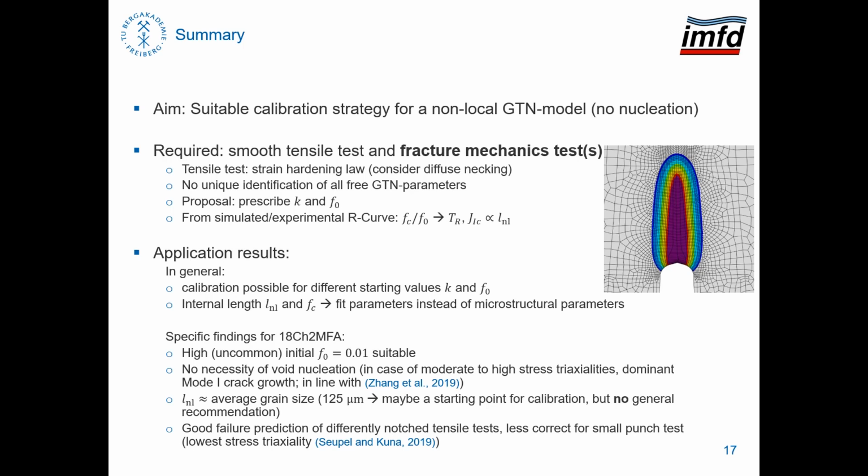For the internal length, a value in the order of the material's average grain size has been found. Using the grain size isn't a general recommendation according to the previously concluded role of the internal length as fitting parameter, but maybe it's a hint for appropriate starting values for calibration.